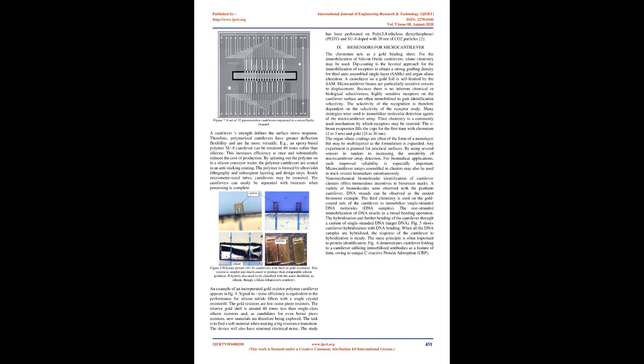The reference cantilever is inert and is used to minimize disturbances from the device, such as variations in temperature. The sensor cantilever is layered with a detector layer on one side that binds specifically with the molecule of interest, as does the reference cantilever. Generally, polyethylene glycol is used to render bioinert the opposite side of the functionalized substrate to resist undesired adsorption. The cantilever begins to bend as the molecules attach on the coated surface, since the surface tension variations between the two sides of the cantilever are different.